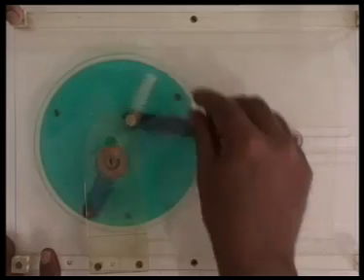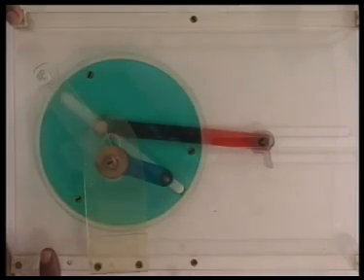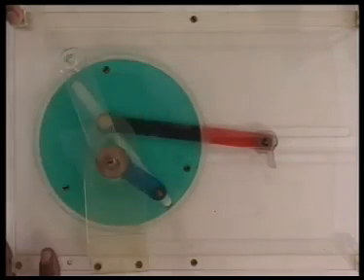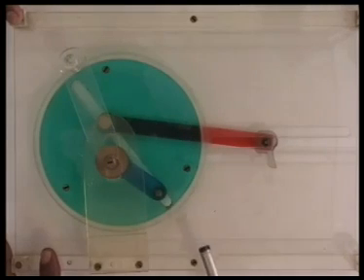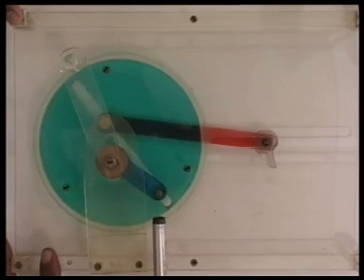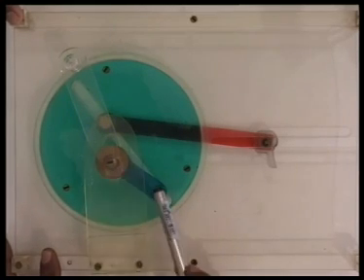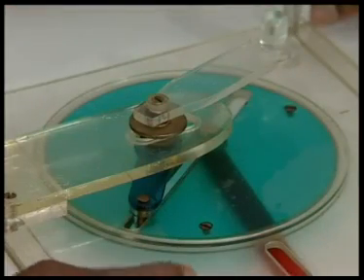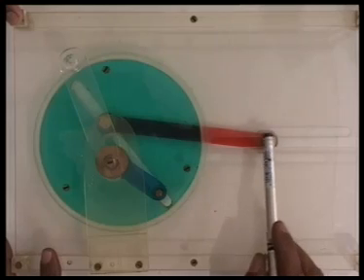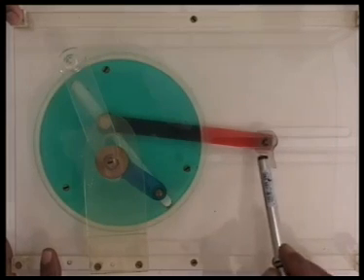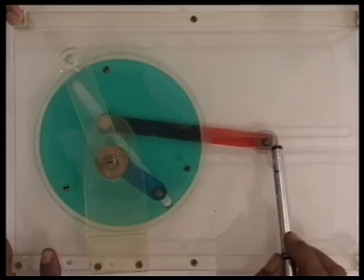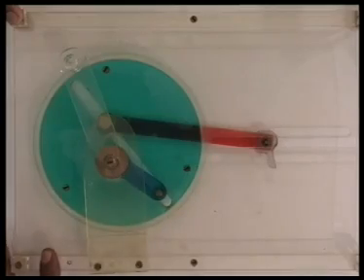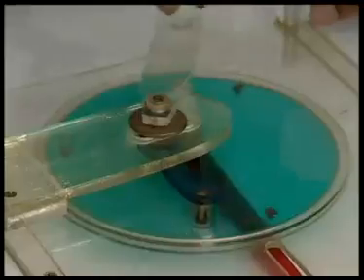Our job is, given this 6-link mechanism at a particular configuration, say this configuration, first task is to locate all the relative instantaneous centers, then second step is, given the input angular velocity at this configuration, say omega 2 is given, what is the velocity of the cutting tool or this tool holder? That is the slider, which will be our link number 6. So this is the problem that now we are going to solve.